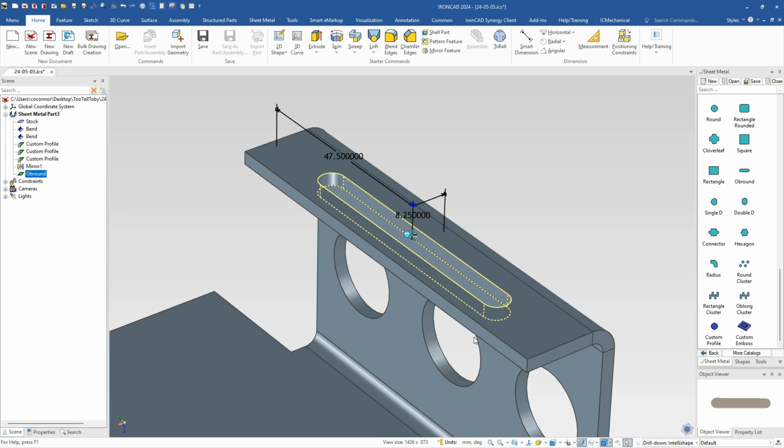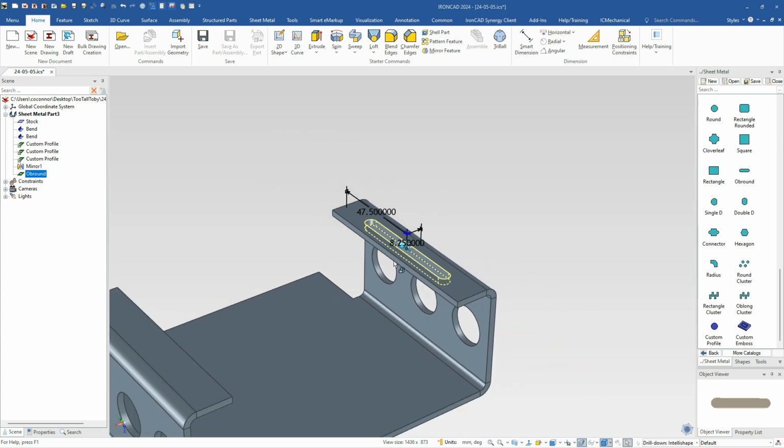So now we've got that in place. We need to position these in the correct location. So in this case, they do have a value of 131 from center to center on that. So we need to make sure that we are in the right location. Let me see if there's one other dimension on that. Hold on one sec. Okay, so yeah, they don't give us another dimension on that, so we'll just use the tri-ball again to position it in the correct location here.